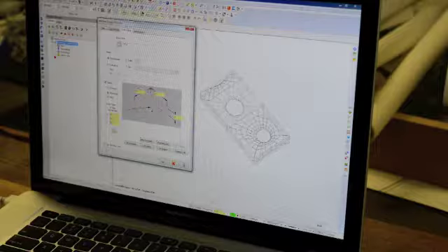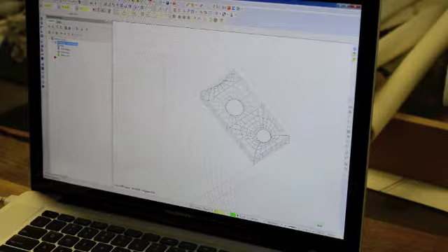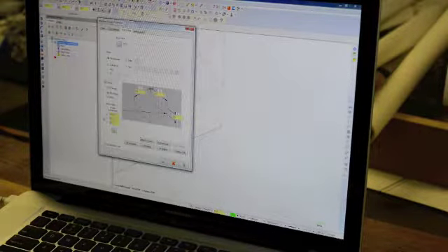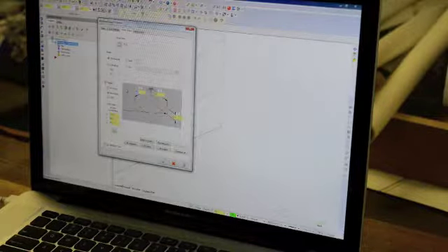We don't want to place the stock in the middle, so just click over here in the corner and we'll set that by hitting the arrow. So stock origin, the coordinates, that's what we need to pick. Come over here, click there. This is the position it's in now, and then we need to put in the dimensions.